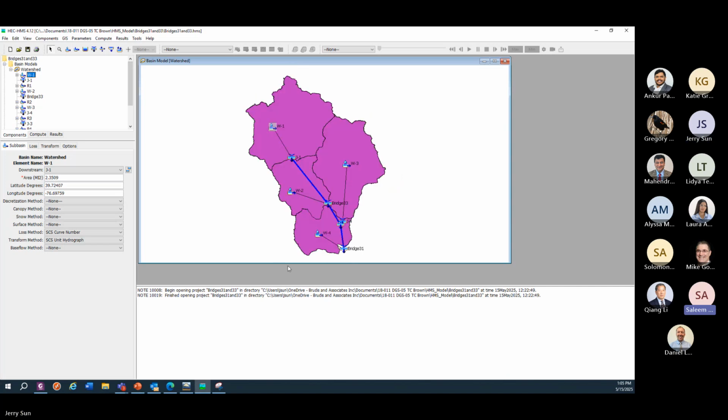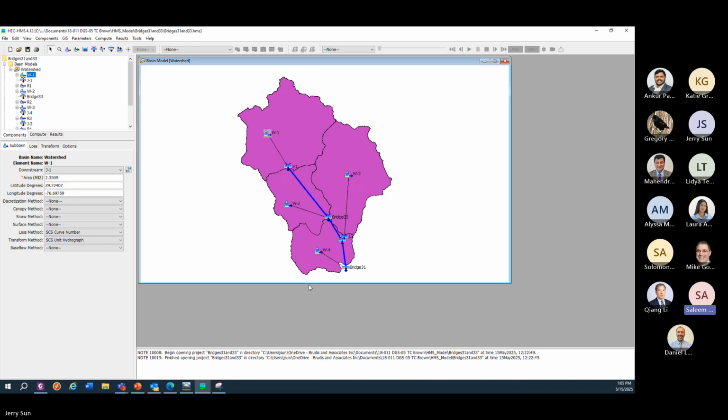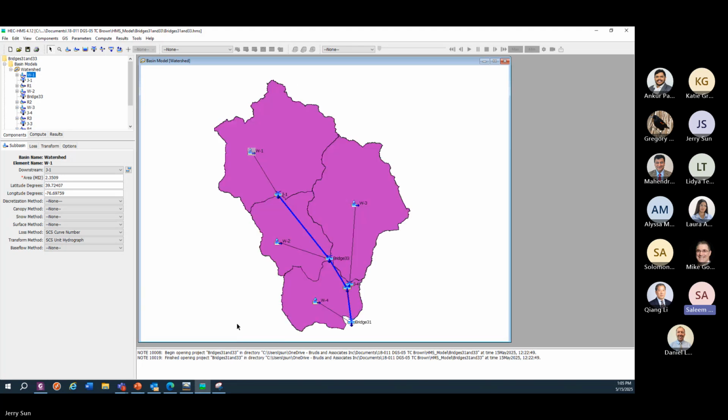Jerry, you have done a good job explaining the TR55 methodology using curve number, and then TR20. Most of our engineers are familiar with the rational formula too. For our day-to-day work on highway design, where we are designing culverts or pipes, the rational method may be appropriate. But when we move into something like a half square mile or 1 square mile watershed, depending upon how much budget we have, we'll prefer to use the TR55 methodology, and we can have one sub watershed.